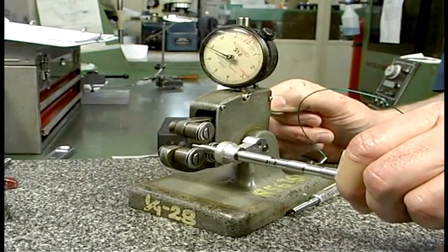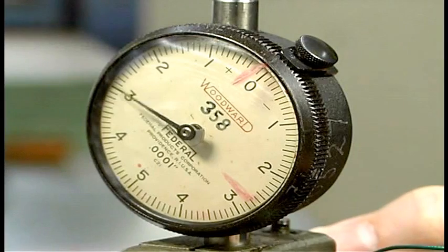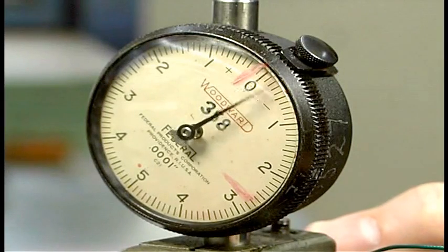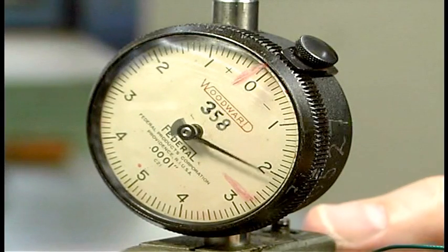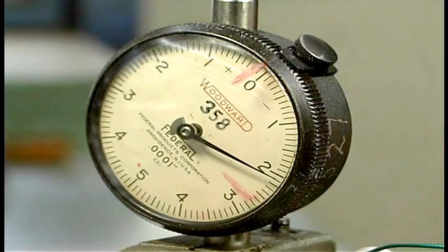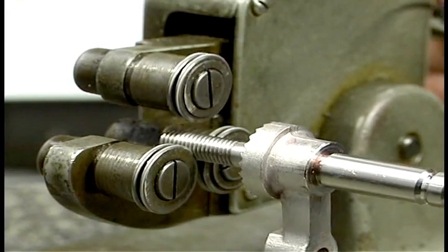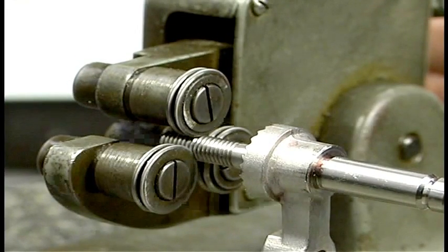Now measure a workpiece. Slowly lower the lever as you count the rotations of the needle. Be sure the same number of rotations occur. Then look at the indicator. The needle must be inside the marked tolerance zone. Repeat the measurement along the whole length of the thread to check for taper.